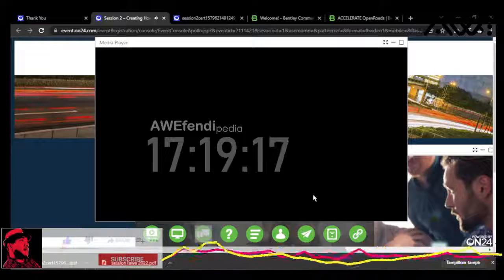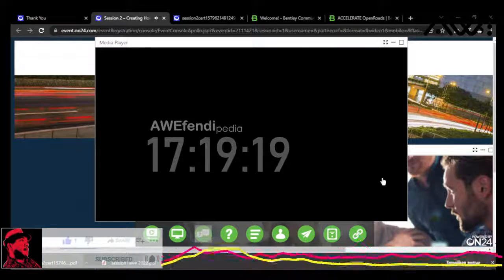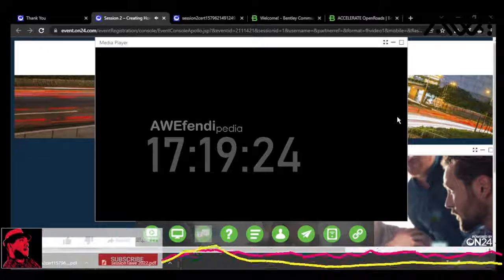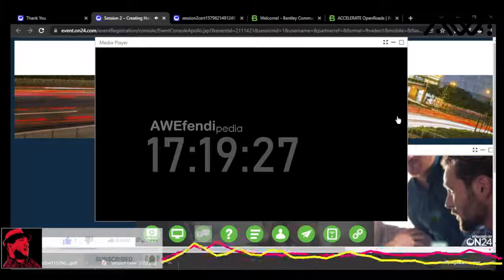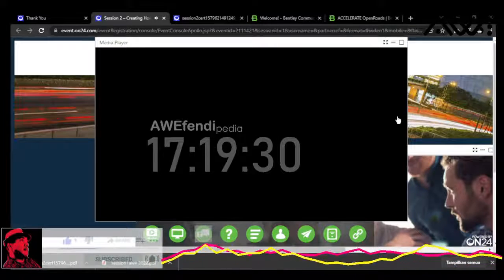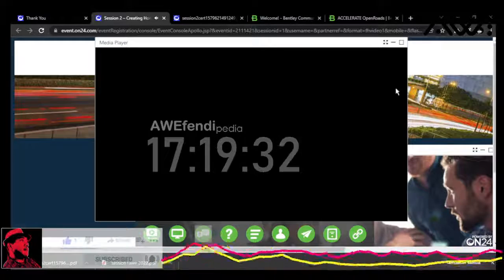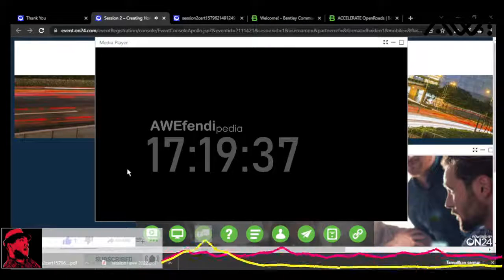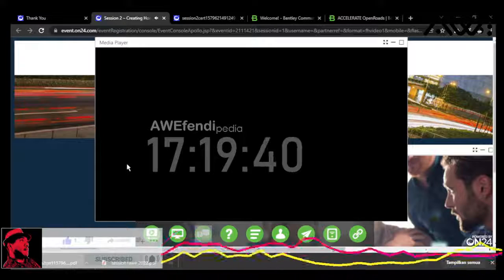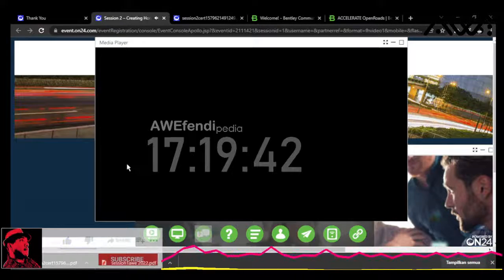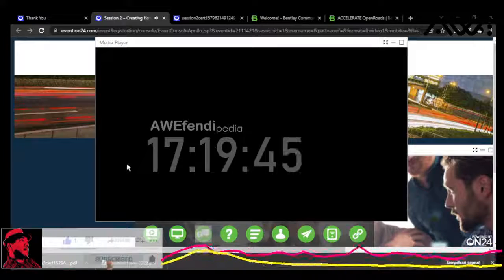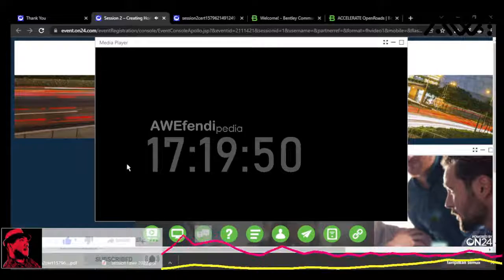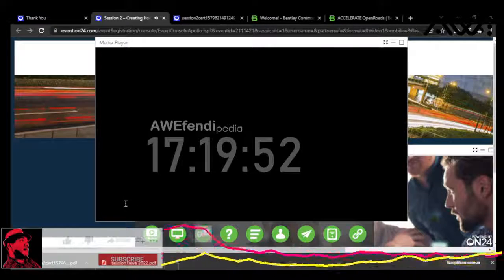Now, before I place that line, I need to point something out, and let me just pull this here to highlight a couple of things. Before we begin to place geometry, it's probably best if you go ahead under that menu and click the Standards drop down. And if it's not turned on already, and it may not be, go ahead and turn on what's called the Feature Definition Toolbar. And that opens up the dialog that you see here. And the Feature Definition Toolbar, we'll use that throughout this session. And you can dock it, as I've done here. You can dock it in different places if you want to.